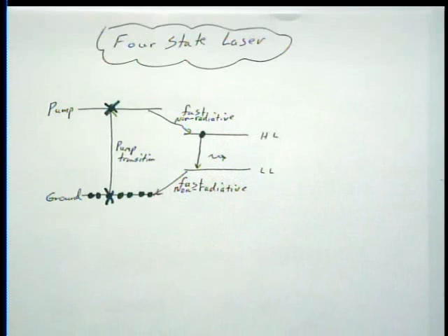Can I change them slightly? If they're molecules and they're in bands, say in crystals, I can dope the crystal. By putting in some impurity atoms, I can change the electric fields in the environment around, and I can adjust these levels slightly. And so, yes, I can build a blue laser or LED if I want for my display by doping it, or I can make it move toward the infrared.